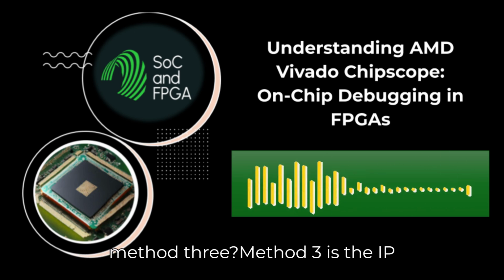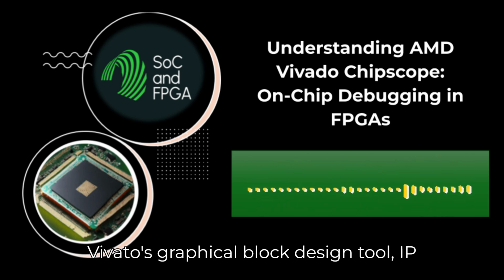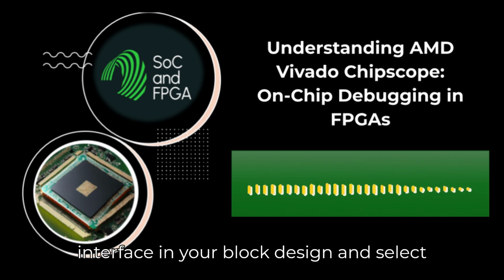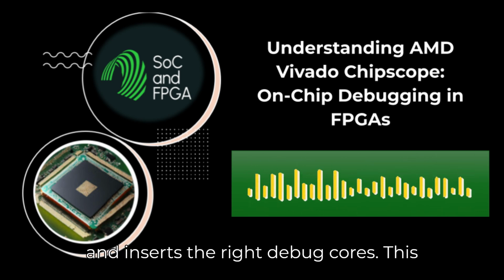Method 3 is the IP integrator flow. This is streamlined specifically for designs built using Vivado's graphical block design tool, IP Integrator. If you're using IPI, you can simply right-click on any wire or interface in your block design and select Mark Debug. Oh, nice. Then during synthesis, Vivado automatically infers and inserts the right debug cores.